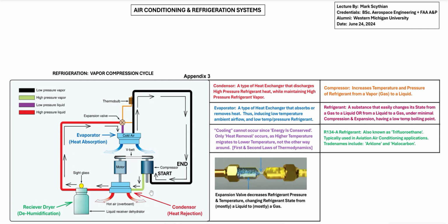So when we introduce compression into the gaseous refrigerant, it will incur liquefaction, or be made into a liquid, while its temperature increases. So our heat exchanger is just a very good thermal conducting structure which allows heat transfer through that structure while not disturbing the increased pressure. So the first heat exchanger, the condenser, its function is to reject heat.